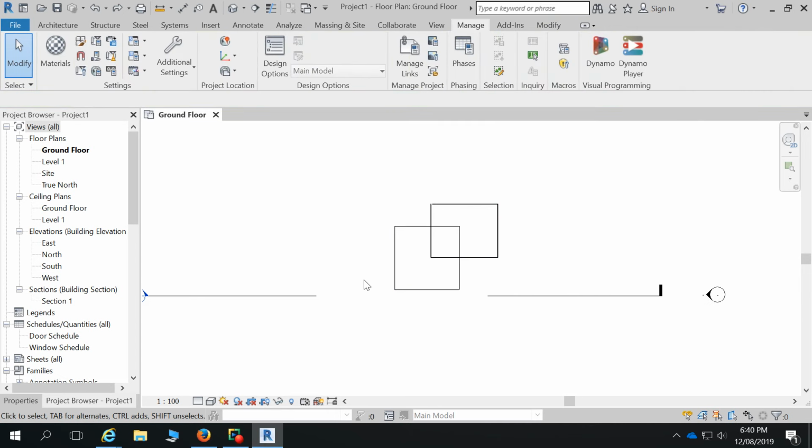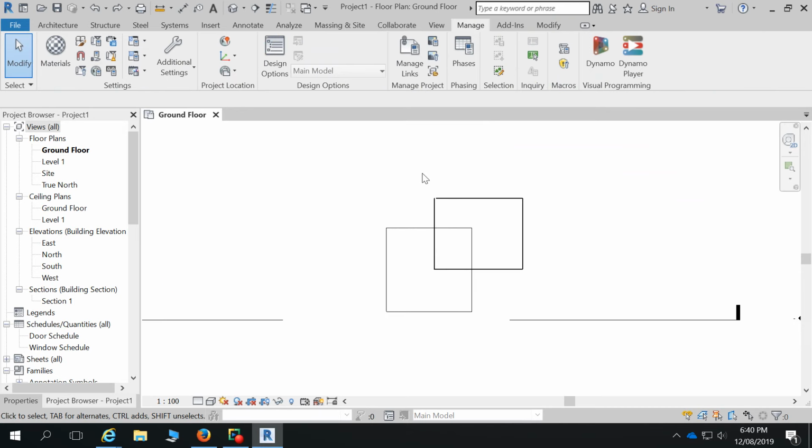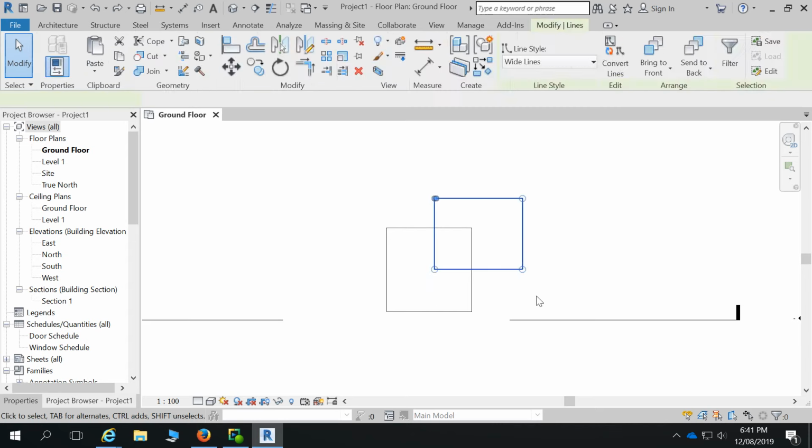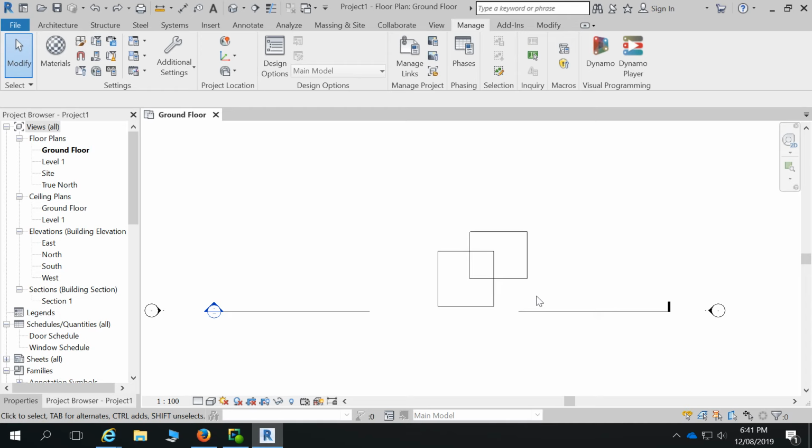If we want to select items, but not all of the items, depending on which way you want to go. So this way would be quite good if I just wanted to delete that box. I could just select that, even though the rectangle was overlaying that other rectangle, it's not enclosed. But if we go from right to left, the opposite way, you'll notice that that window is a dashed line. Now when we use the dashed line going back the other way, anything that I touch is selected. It doesn't have to be fully enclosed in that window, okay? So that's sort of known as our selection window.